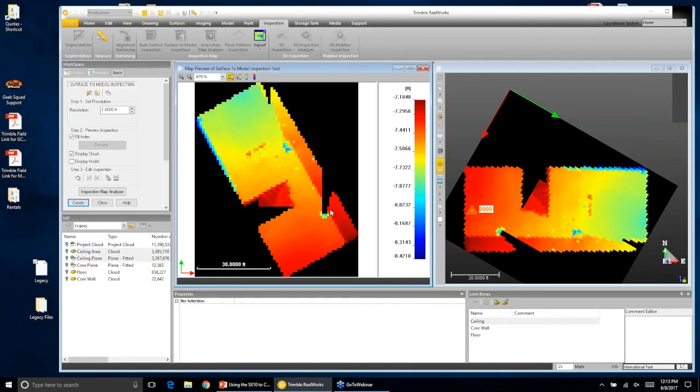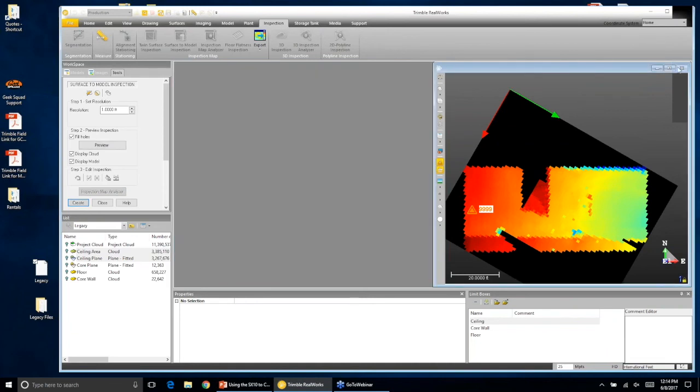So you have very quickly, very easily a tool for doing the comparison of point cloud data, if there's any humps or dips in the floor, and then you create the plane from the model information, and then compare the two, the model and your flat plane, and you know exactly what's going on with your surfaces there.